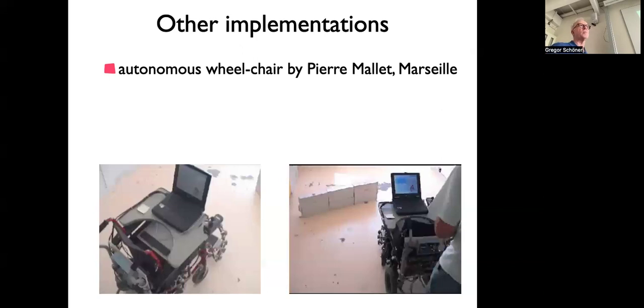And sometimes you still can have intermittent control. That is, every now and then you give a new target to the robot. That's what the system was like. The system would always have a target that was a few meters away, and you could update that at discrete times, whenever you have a chance. You can have different interfaces for that. And it would just move to this target and do obstacle avoidance based on a lot of these low-level sensors. See, there are these sensors. They were mounted all over the place. We had dozens of those sensors.